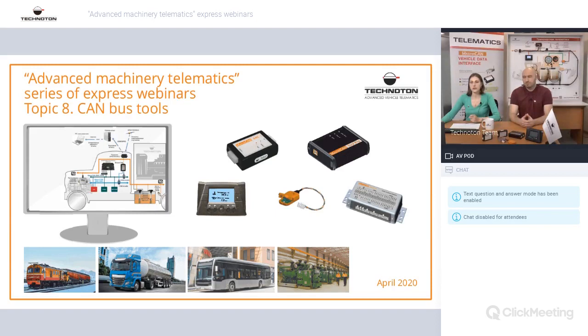As for output messages in the electronic CAN bus of the vehicle, there are actually plenty of them, but the most useful for telematics are engine speed, instant fuel consumption, trip fuel consumption, engine temperature, oil pressure, engine torque, coolant level, oil level, or even fuel level.